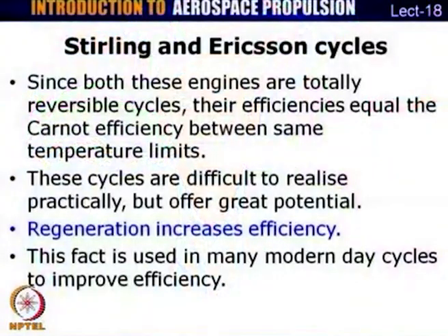are very cumbersome in nature. Though these cycles have been demonstrated in some way, of course, there are some irreversibilities which will still take place, but these cycles did have very high efficiencies, higher than the normal Otto and diesel cycle efficiencies. But they are extremely cumbersome to build, and obviously, they still cannot achieve Carnot efficiencies. But the main aspect of Stirling and Ericsson cycles is that regeneration increases efficiency.